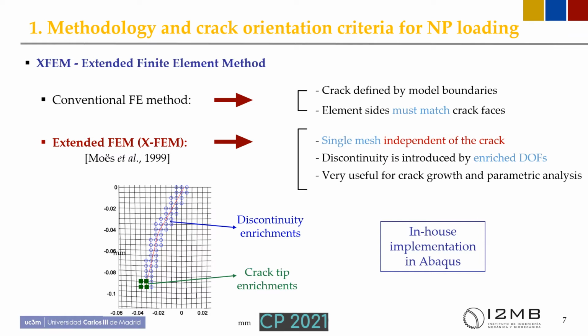We have used an in-house implementation that introduces crack face contact and also a post-processing subroutine to calculate the stress intensity factors via interaction integral.